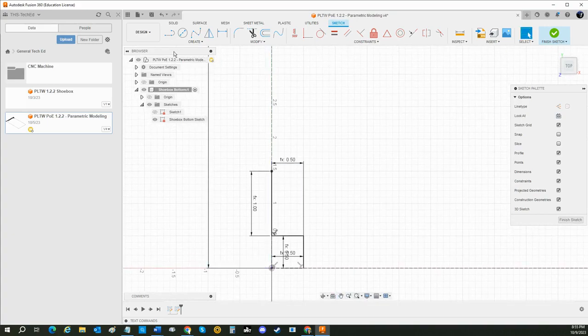And then I'm going to come back down off this endpoint, the thickness, THK. And I'm going to finish off this repeatable piece from my endpoint at my W end. And there we go. So I now have stuff here that is completely repeatable. So I'm now going to go ahead and create a pattern.